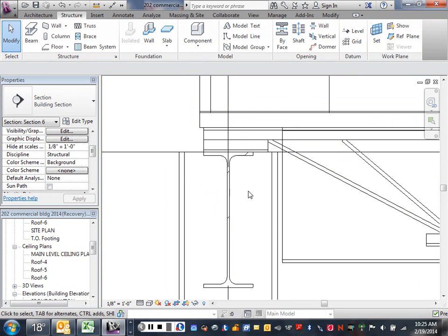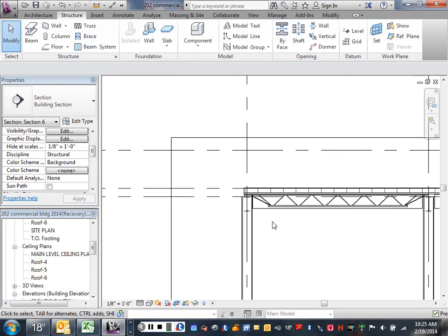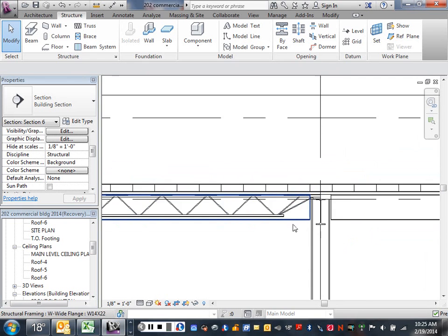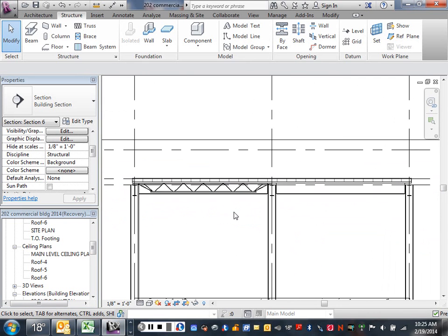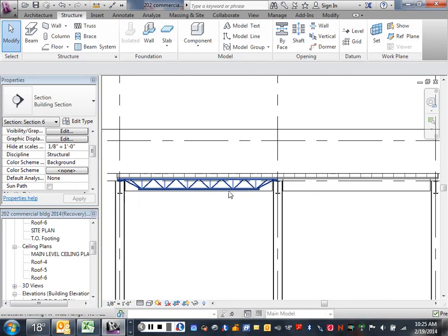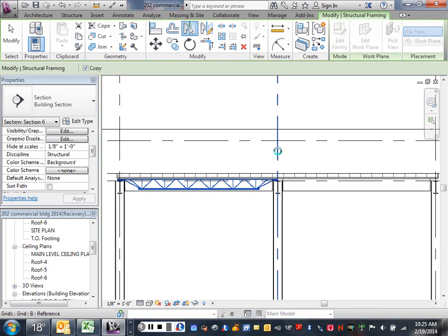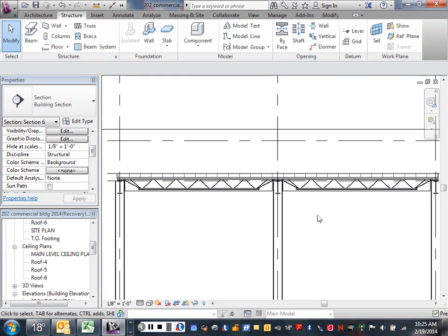On the other hand, over here, on the ending extension, I have another bar joist that's going to come over and butt into this one, right? So I don't want that one to bear any farther, maybe just the outside one. So in this case, I could take this bar joist and mirror it on that point. And now I have them both on, right?